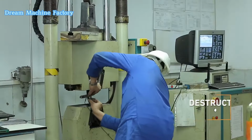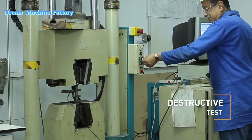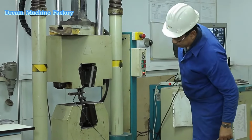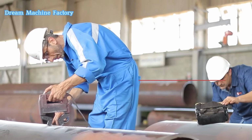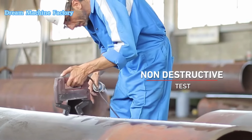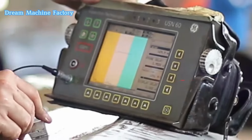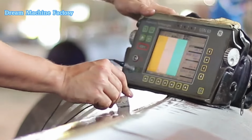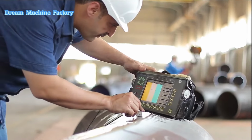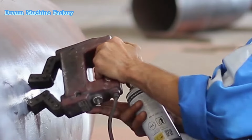To verify the strength and durability of the welded joints, destructive testing is performed. This involves applying extreme force or stress to a sample weld to check for weaknesses. In addition to destructive testing, non-destructive testing (NDT) is carried out to detect defects without damaging the structure. Methods like ultrasonic testing, magnetic particle testing, and radiographic testing help identify internal flaws in the welds and steel components.